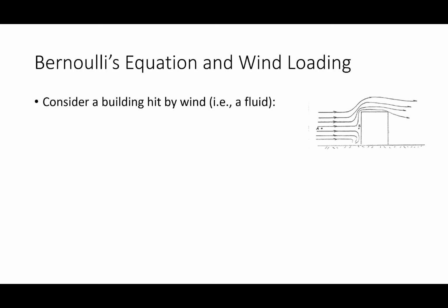And where it comes from is Bernoulli's equation, okay? So what I want to do is consider some sort of building that's being hit by wind, and we're going to treat wind like it's a fluid, okay? So I'm going to consider two points on my schematic. I'm going to consider point A, where the wind is flowing, and point B, the stagnation point, where it's hitting